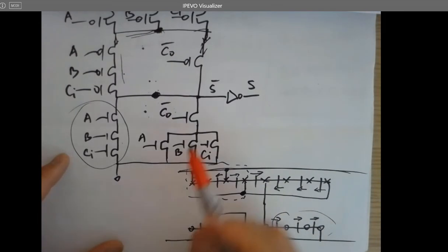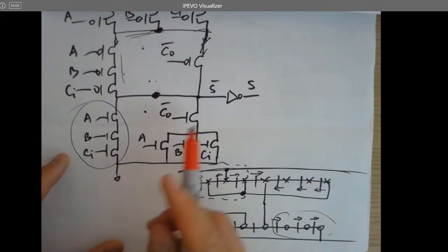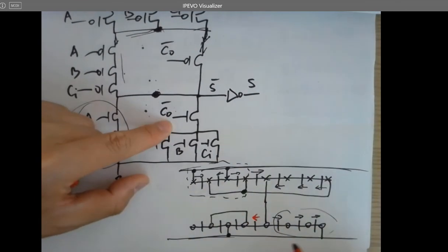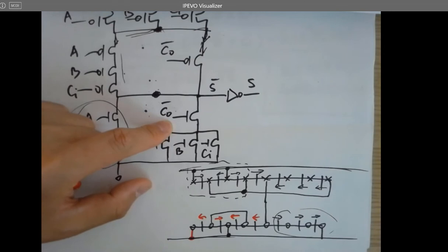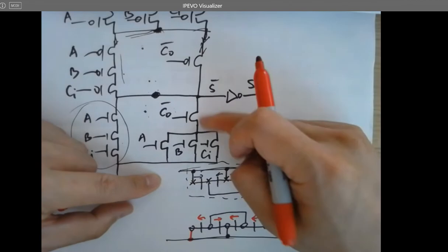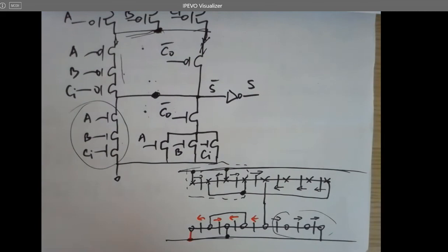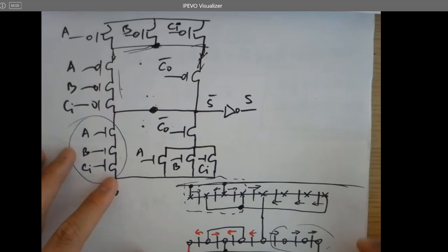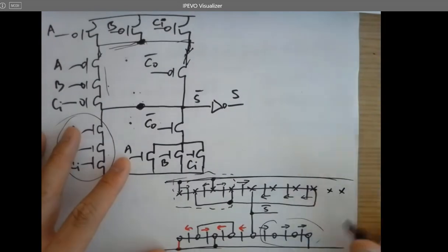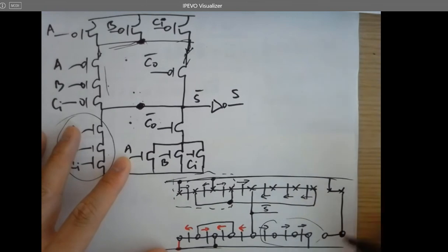Because I want to implement this logic, I need to run through a NMOS first. So go through this NMOS first, and then 3 NMOSes in parallel. Right? 1, 2, 3. So I want to short this to ground as well. So this part is 3 NMOSes in parallel, and this part is this little NMOS here. That's how to design this part. And that is S0. And to invert it, just directly add an inverter after it. So here's S.